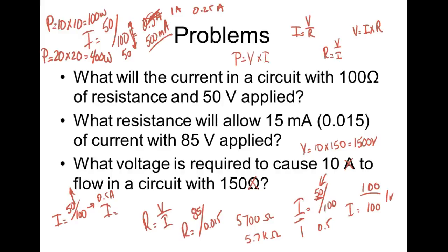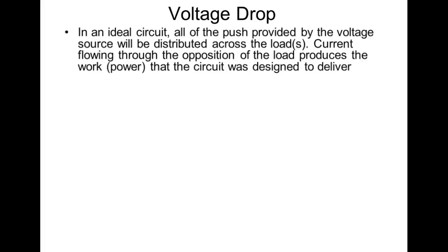You understand? So power does not vary with voltage. It does not vary. It varies with the square of the voltage, right? You understand? If it goes up, it's times the square. If it goes down, it's 1 over the square. And that's why it don't take much voltage drop to cause big problems in a circuit.